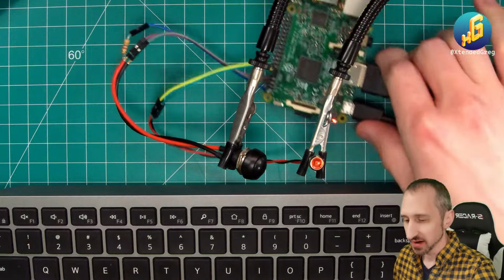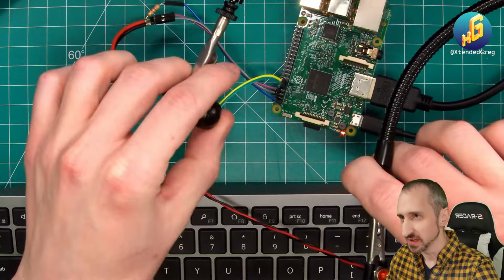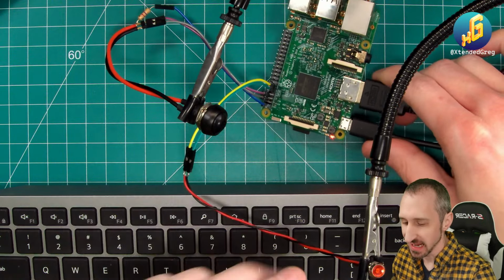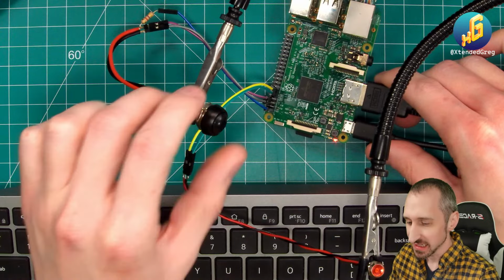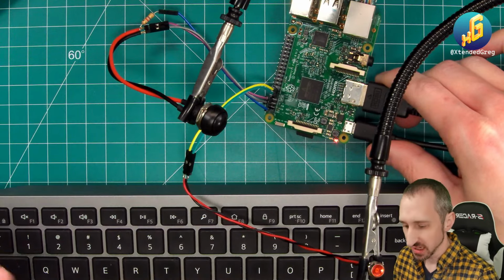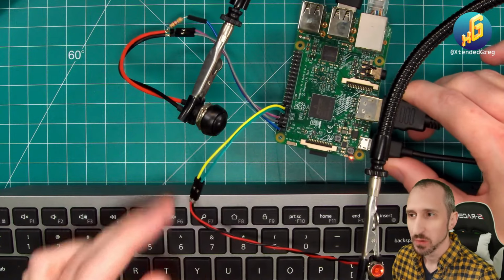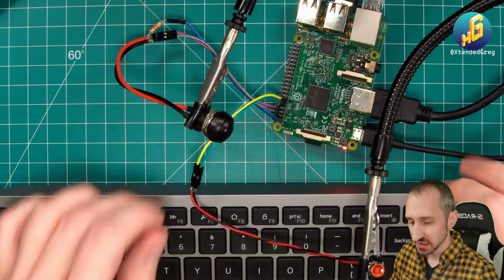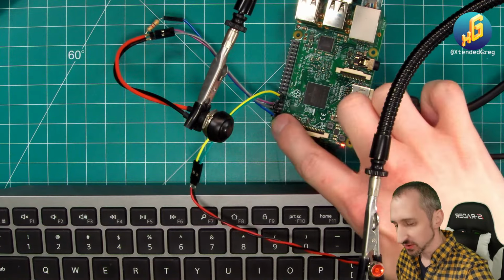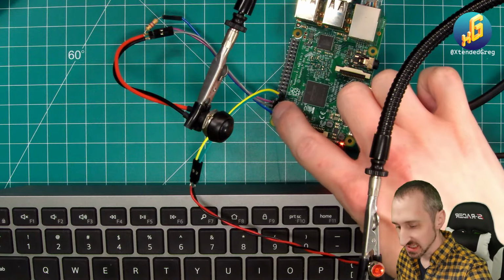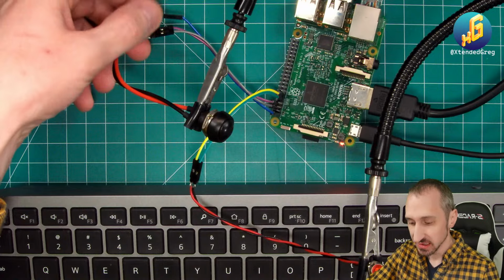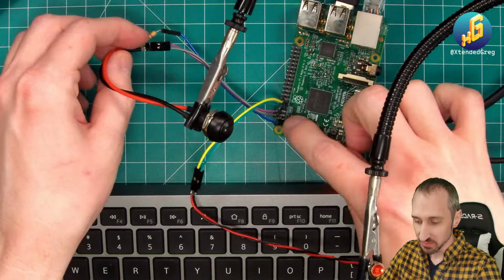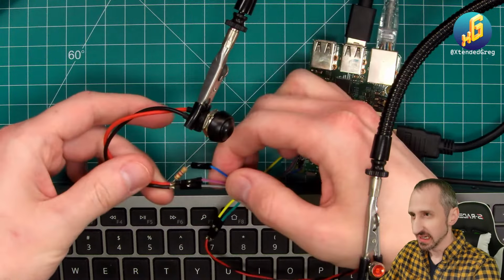So what I have right here is a Raspberry Pi 3B+. I'll move this away a little bit, but pretty much I have an LED already connected to it, as well as a button, so that way we can test input and output. The LED is just directly connected between one of the pins and ground, and the button is connected to 3 pins. It's connected through a resistor, I should say, to the 3.3 volt line. It has a connection to the pin that is literally in parallel with that.